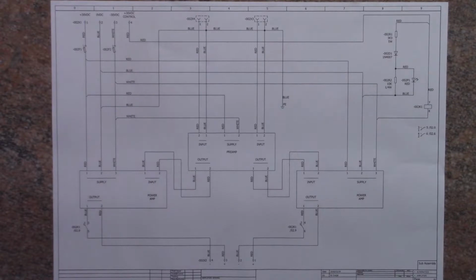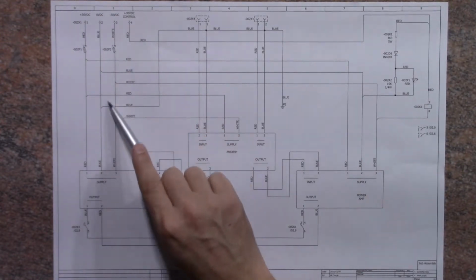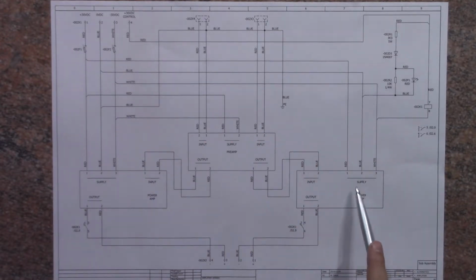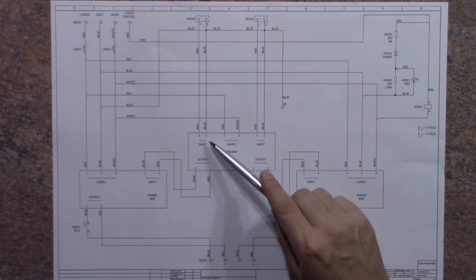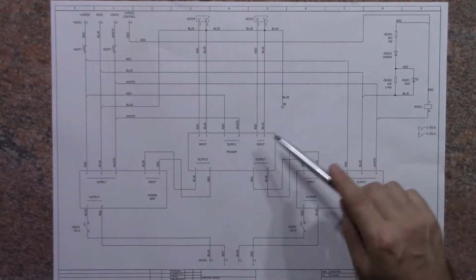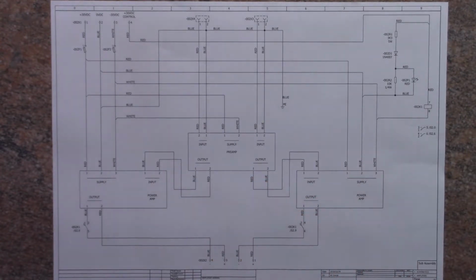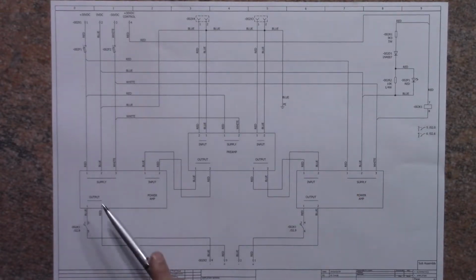This is the schematic for the point-to-point wiring of the amplifier. It starts off with the plus and minus 30 volt supply through fuses, goes to the left hand side power amplifier and to the right hand power amplifier and to the pre-amplifier over there. The left hand channel of the pre-amplifier is wired to be 180 degrees out of phase. The right hand side is in phase, and the output of the preamplifier goes into the left hand side of the power amplifier, the output here to the right hand side of the power amplifier, and then the output goes